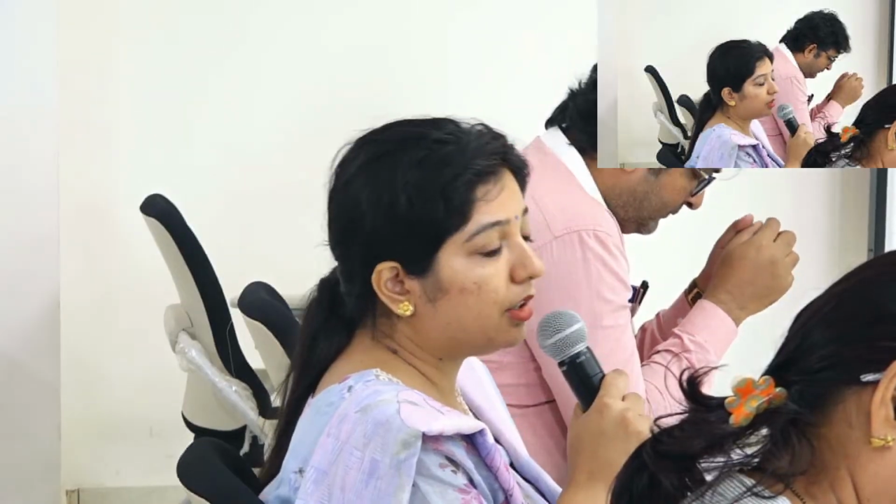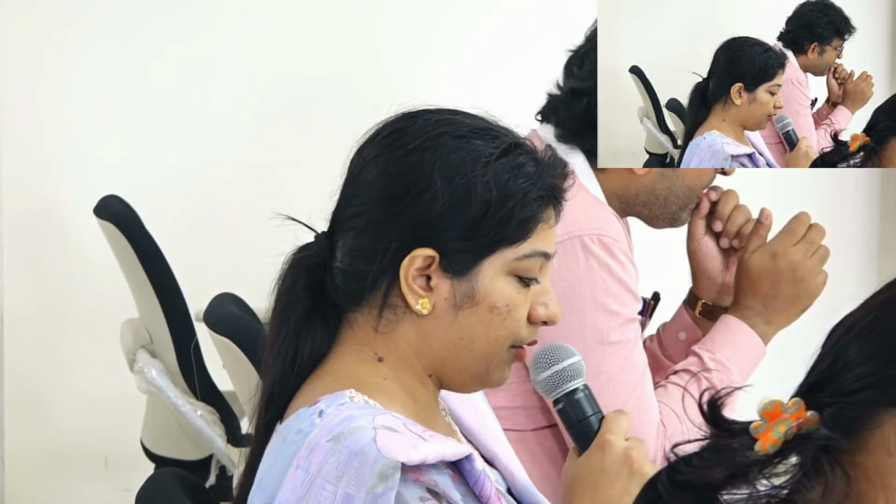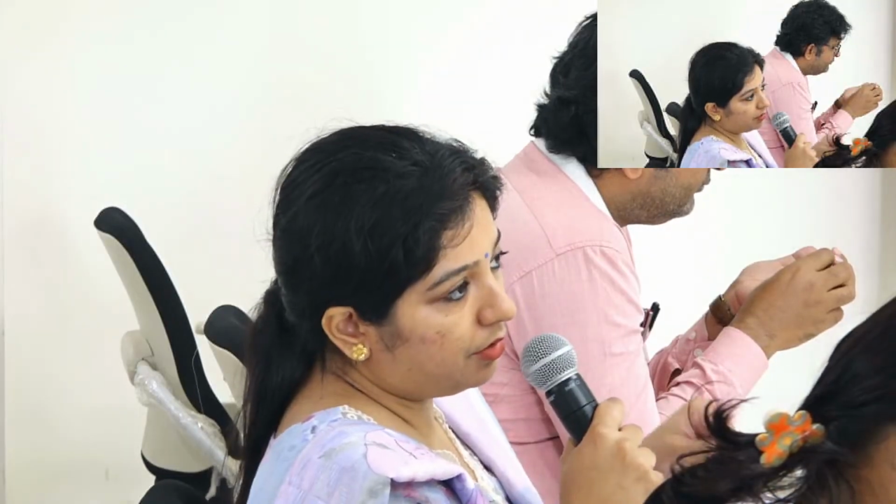Sir, I have a question with respect to yesterday's session. The short circuit ratio has to be checked at the point of common coupling when we are in these stages of deploying the microgrid. Where does it stand among all the tool development stages? Also, when we are having the microgrid point of common coupling with the grid, the short circuit ratio is the same, it has to be equal to or greater than 3 in this case also. Yeah, again, it should be the same idea.